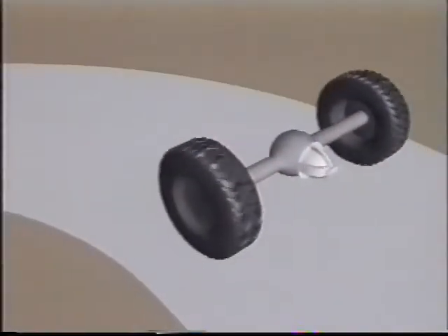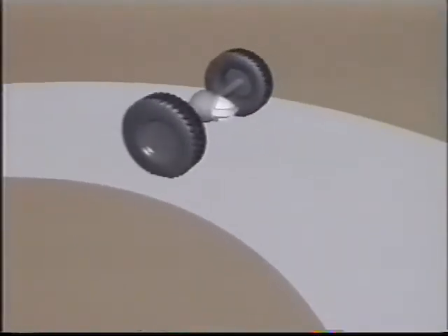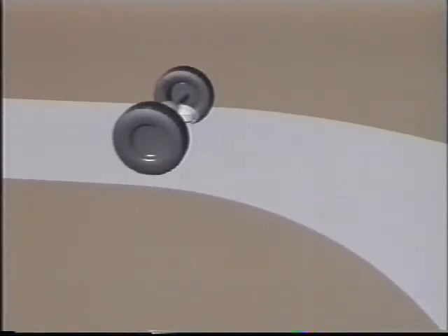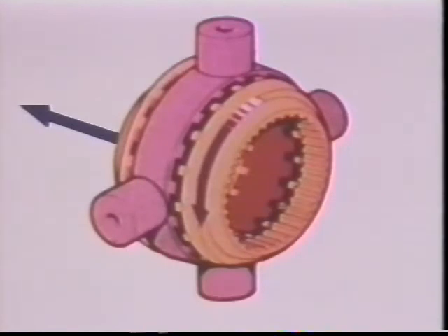When the vehicle goes into a turn, the outside wheel, pushed by the swing action of the turn, is allowed to disengage and turn faster than the inside wheel to cover this longer distance in the turn. The inside wheel continues to drive the vehicle through the turn.